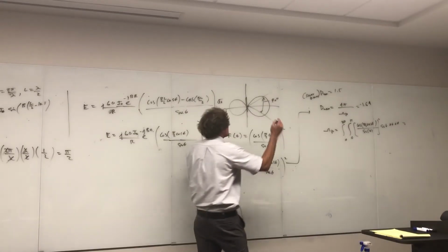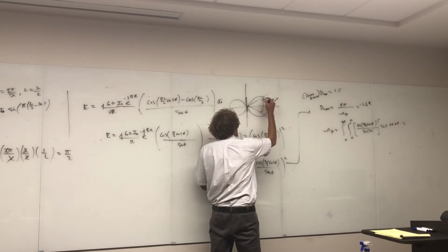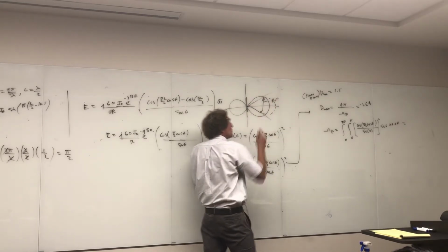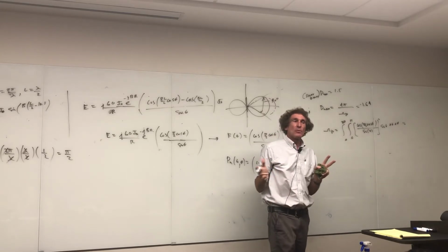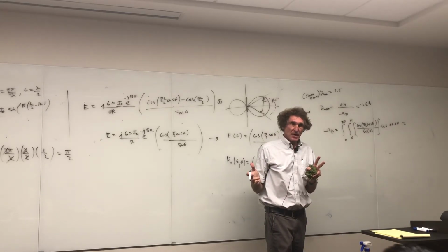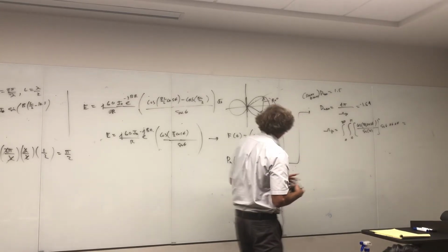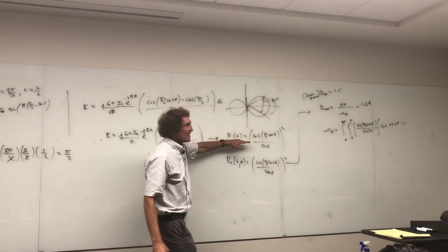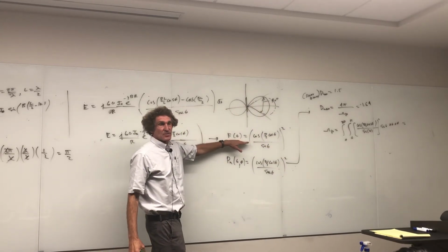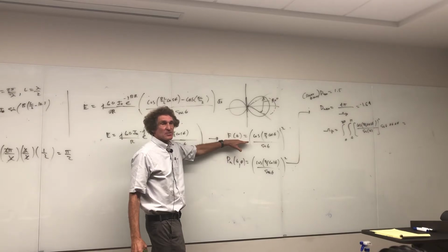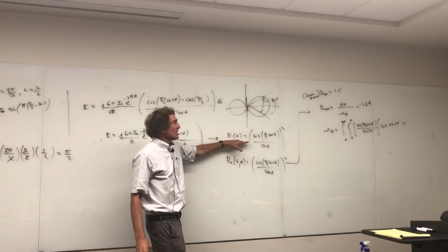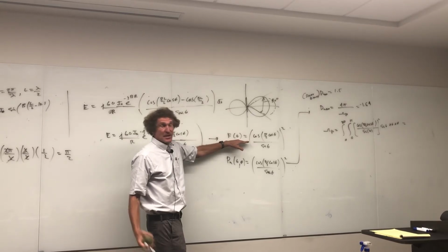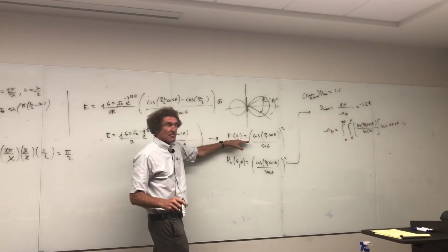When you do the half-wave dipole, it's just a little bit better. The beam width is going to be a little bit less, but not much less. And you can figure it out, but the way you have to figure out that beam width is you have to take this and set it equal to 1/2, and then solve for that angle. And there are two angles. It'll be symmetric. The beam width is very slightly better. Instead of being at like 45 degrees, it's like at 48.3 or something like that. I'm not kidding either. That's how slight a difference it is.